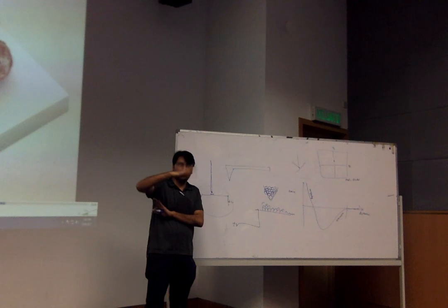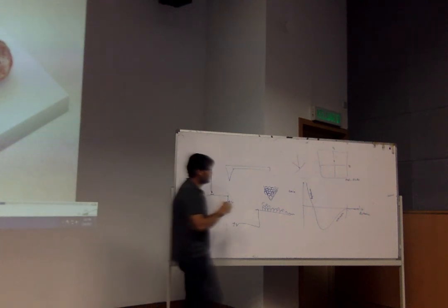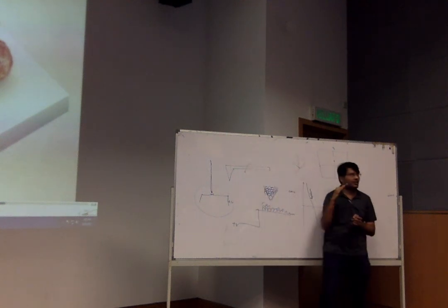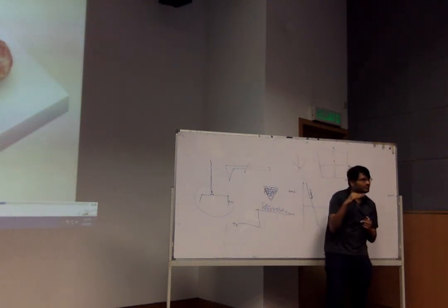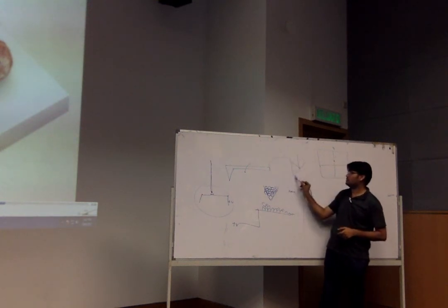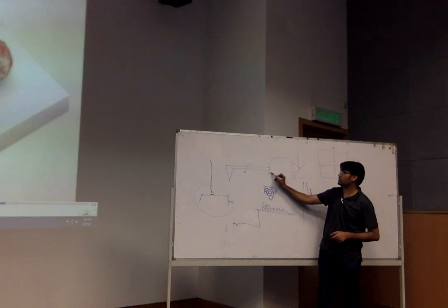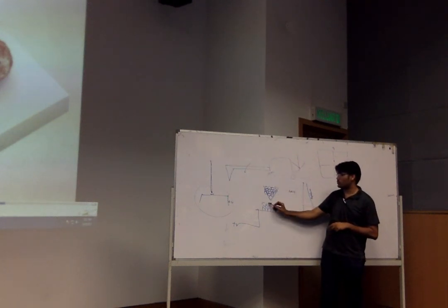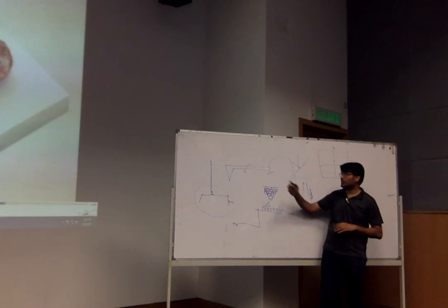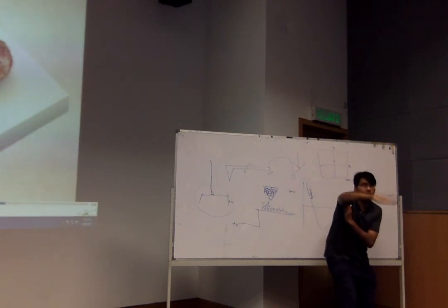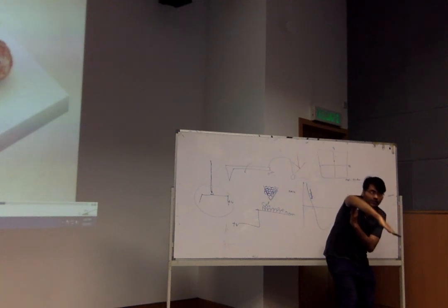Now when it comes closer and there is bending, the resonant frequency gets disturbed. Say the oscillation frequency was 50 Hertz. When the distance became smaller, the vibration frequency changed because the beam got bent, so the resonant frequency got affected.